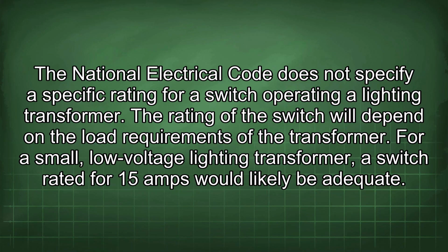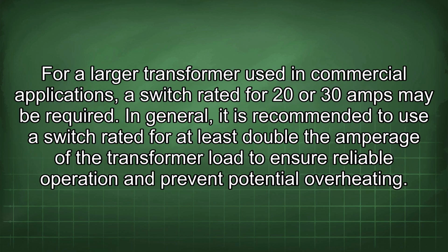The National Electrical Code does not specify a specific rating for a switch operating a lighting transformer. The rating of the switch will depend on the load requirements of the transformer. For a small, low-voltage lighting transformer, a switch rated for 15 amps would likely be adequate. For a larger transformer used in commercial applications, a switch rated for 20 or 30 amps may be required.